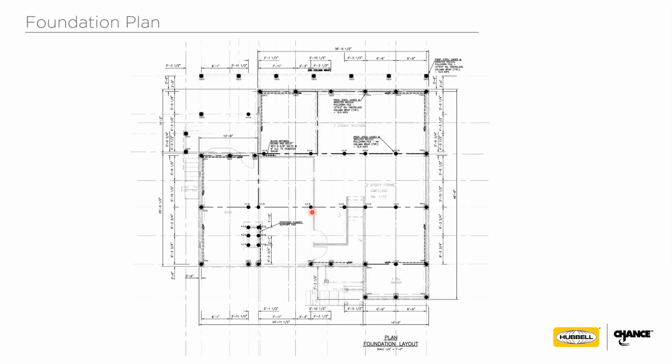So what you're seeing here is kind of a plan view of the eventual structure. It's kind of hard to tell. Obviously, this is the vertical pile locations. This is where the chimney was or is. And here at some of these corners, you can barely tell, there are these dotted lines. The pile engineer or the foundation engineer decided to put in some lateral anchors, battered anchors, in order to resist additional lateral forces, over and above what he used for the piling itself.